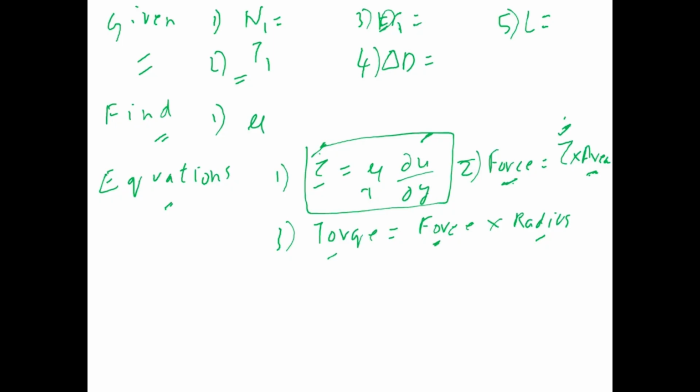So this goes back to how you find velocity now that you know the rotations. You have not been explicitly given velocity, but instead you have been given how fast the cylinder is moving. Hopefully students know how you can find linear velocity from revolutions per minute. RPM is just the number of revolutions, or essentially how many 360 degrees the cylinder is making every minute. One revolution is 360 degrees, so how many of those revolutions are you making per minute?